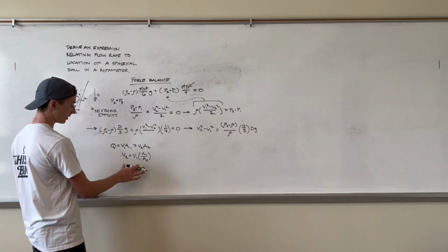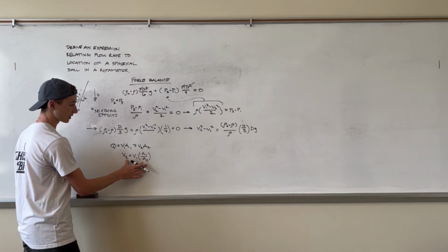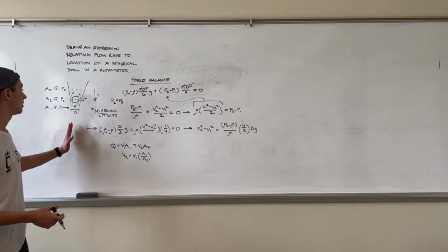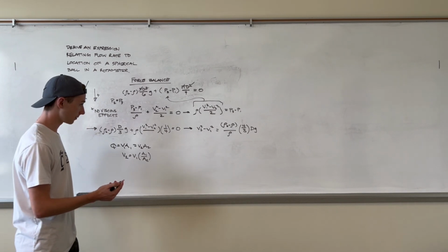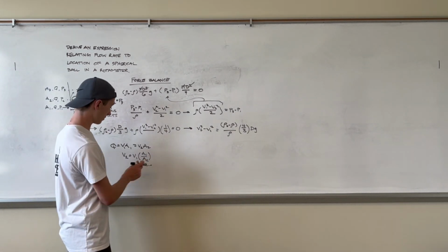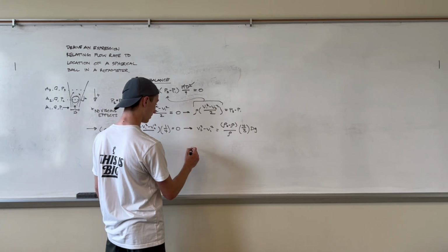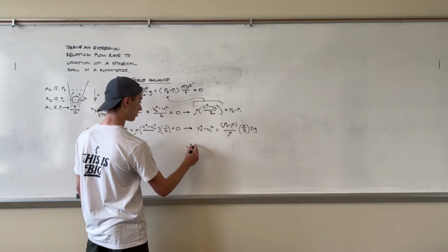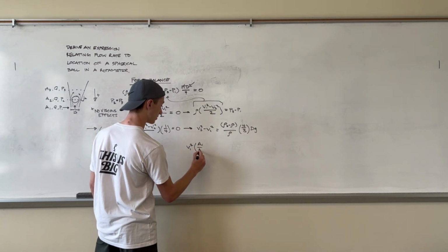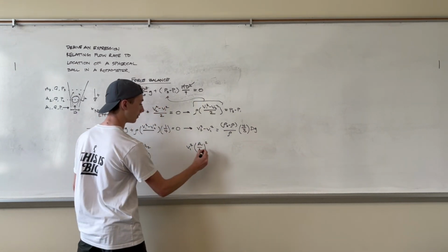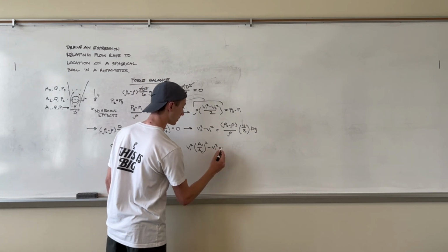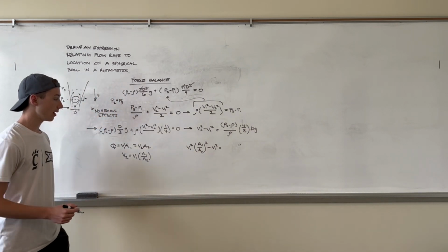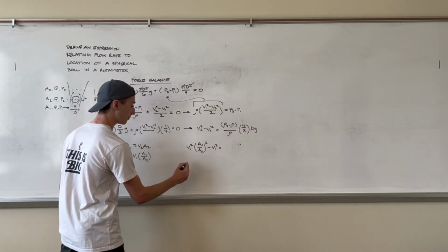And then what we can do now is take this and substitute this expression in for V2. So we're left only in terms of V1, or our initial velocity of the air there. So we get V2 squared becomes V1 squared times A1 over A2 squared, minus V1 squared, equals this side. And then we can factor out a V1 squared.